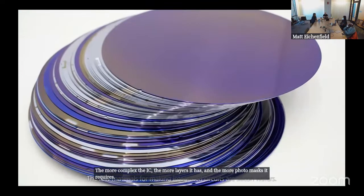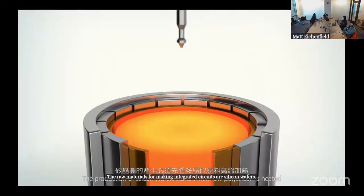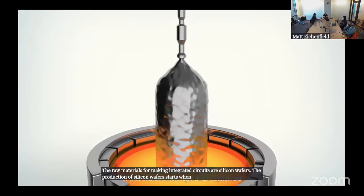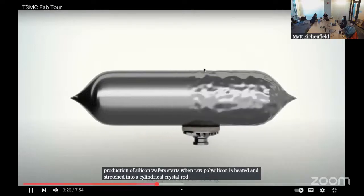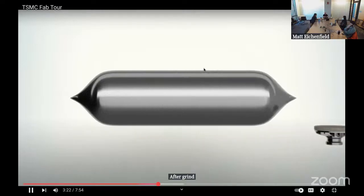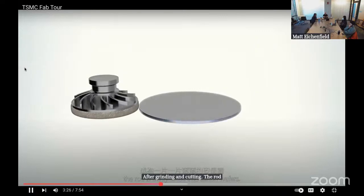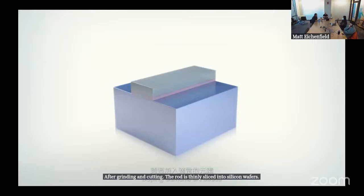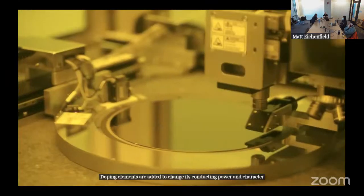The raw materials for making integrated circuits are silicon wafers. The production of silicon wafers starts when raw polysilicon is heated and stretched into a cylindrical crystal rod. After grinding and cutting, the rod is thinly sliced into silicon wafers. Doping elements are added to change its conducting power and characteristics.